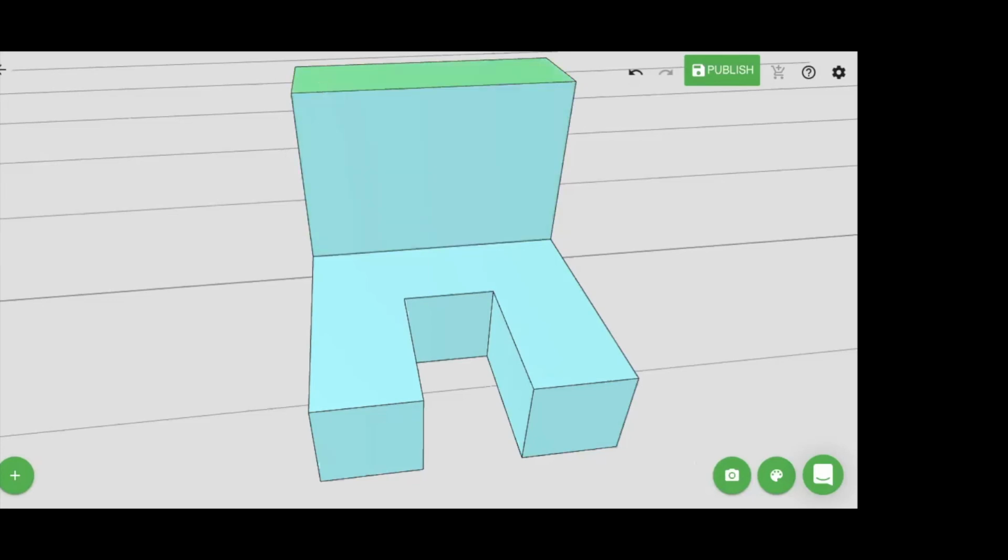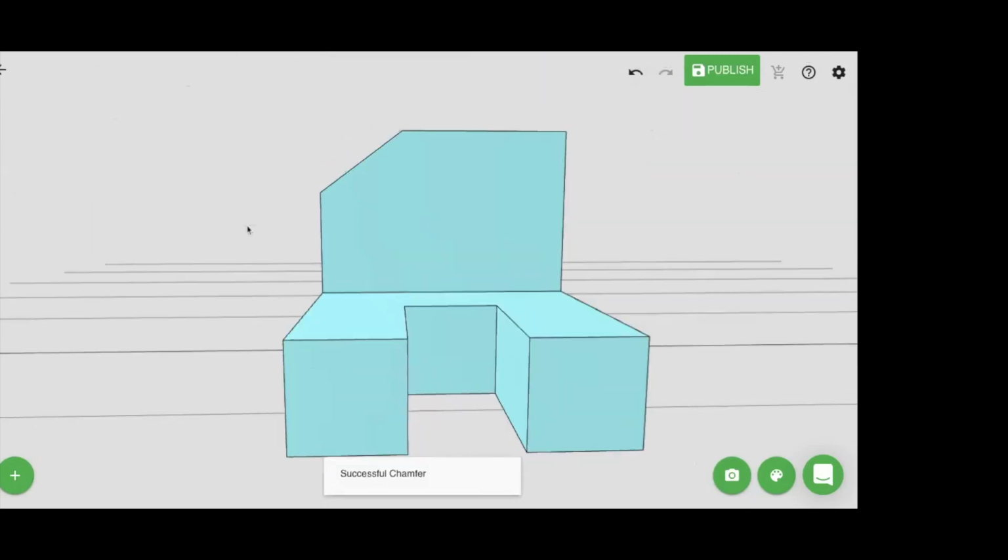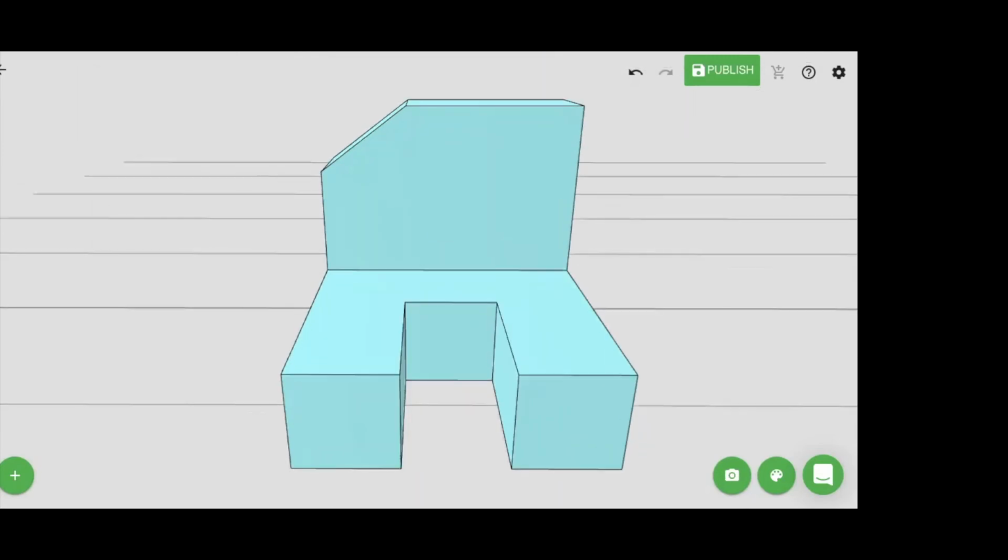So to handle that, we select this face, and then we hold Control and select this edge, and now press this, and now we can do two different dimensions. So one of the distances was 1.5, and the other one was 2. And so in doing this, now we make this kind of weird, wonky side cut, and there we have it.